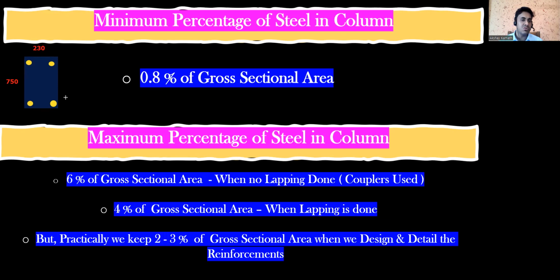So what has happened in between these two rebar? What is the spacing coming out? Overall, it is 750. If I take out the cover and all directly, I'll do it for you. So 750 is the overall depth. It's a column, right? So you take 40 mm cover out from the top, 40 mm from the bottom. Then you have a stirrup of 8 mm, from both the sides, I'm taking it out. We are going center to center, okay?